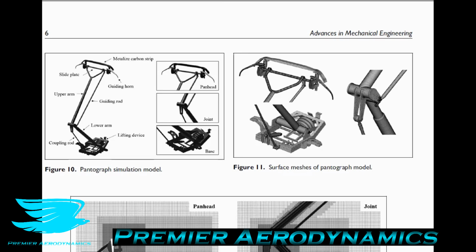It means that you can use fewer voxels in the entire domain and still get an accurate simulation, whereas other software, including open source ones, currently don't usually allow you to have different voxel sizes. So that means if you want to have an object highly resolved, then the entire domain has to be highly resolved too. So you get a lot of voxels that you don't need. But unfortunately, that's an artifact of the equations, the simple equations.